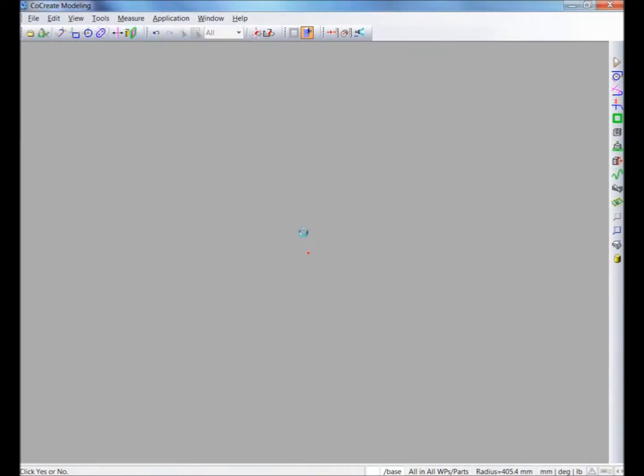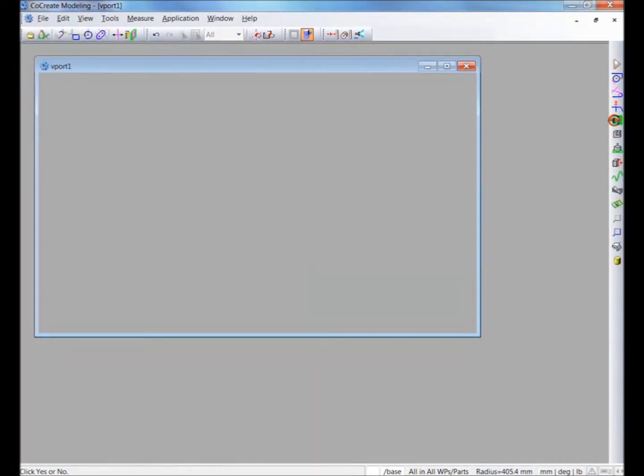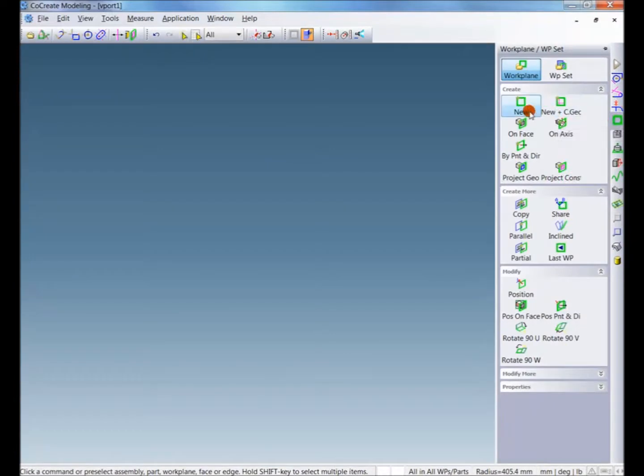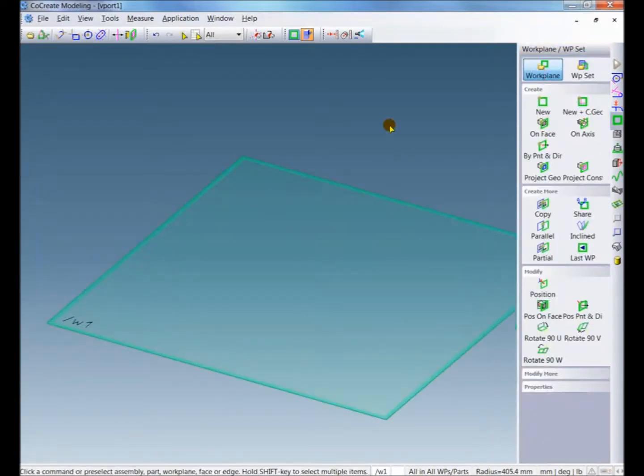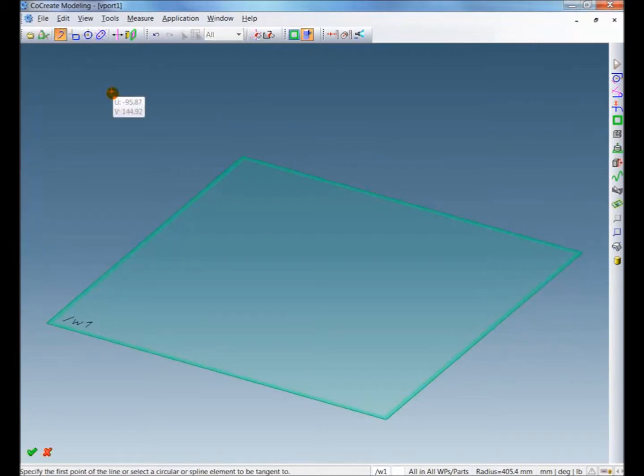To get started, I'll create the design from scratch, and as the design matures, leverage and repurpose existing components from my database. These types of products have short life cycles and require rapid and innovative design. I'm beginning the design of the case for the media player. I only have a basic idea of what I need, so I'll start with a symmetrical part and get some geometry laid out quickly. With explicit modeling, the profile is only used to create the 3D model, and then you can discard it. I spend very little time drawing and go quickly to a 3D model that can be manipulated as the design progresses.